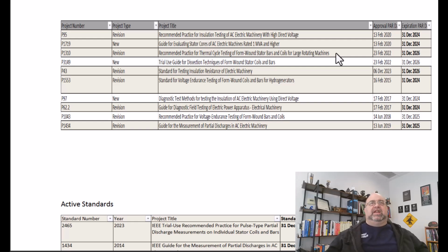Capability was that it basically allowed up to 50% harmonic distortion in current, all in the fifth harmonic, counter-rotating field. And contrary to what 519 says, every machine in that branch was absolutely affected.